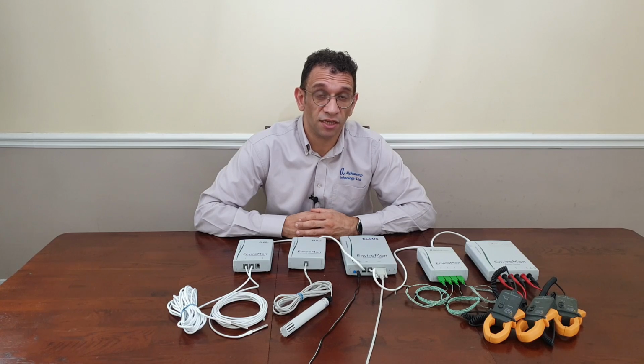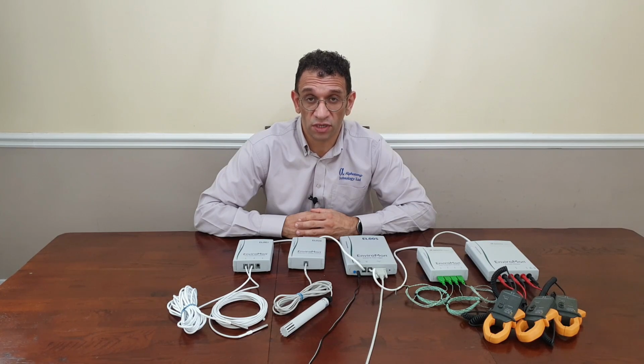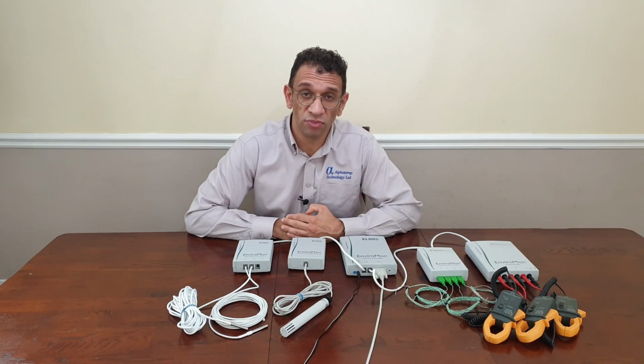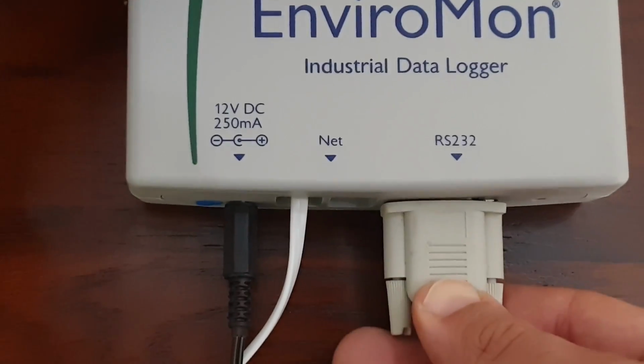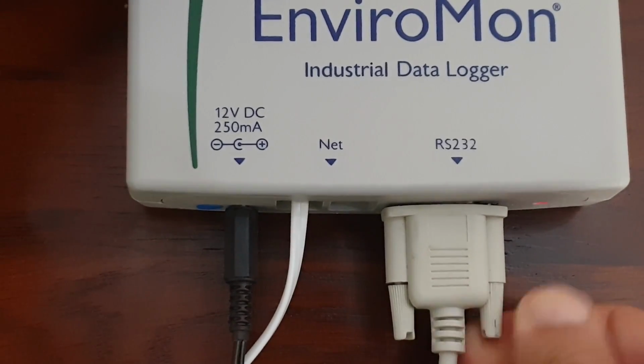Failing that, you may need to run the logload software, which will reprogram the firmware on the data logger, but I'll cover that in another video. Obviously, the connecting serial cable and adapters could cause a comms issue if they're not securely connected or damaged in any way. So have a visual inspection of the cables to assess any damage, and ensure that every connection point is securely connected.